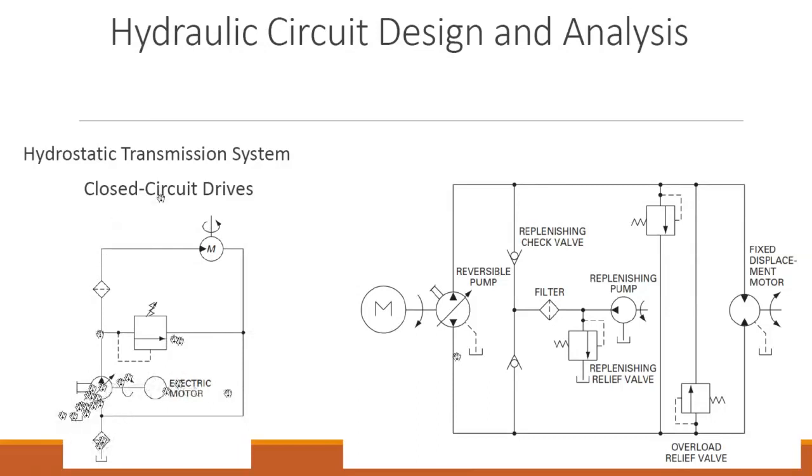An electric motor is running the pump, and the oil comes here. The oil stops here because there is not enough pressure to open the pressure relief valve. This arrow at the spring shows that this is an adjustable pressure setting in this type of pressure relief valve. So you can adjust it based on the maximum pressure allowable in the circuit.